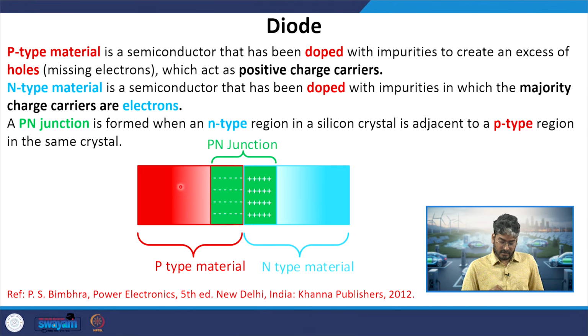Now we will have a single substrate of semiconductor. Then how is this PN junction formed? We inject impurities into the semiconductor to form a particular P or N type layer. What is a P type layer, and how is it formed? It is formed by a method called doping. What is doping? Adding impurity into the semiconductor material. What impurities will be used here?